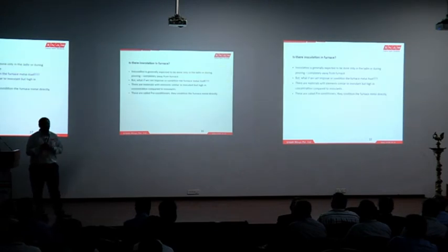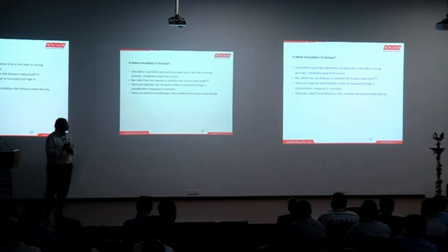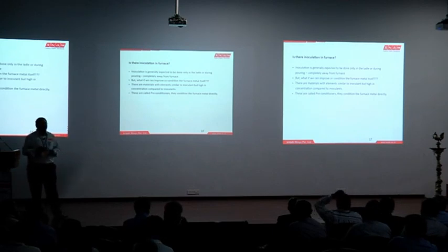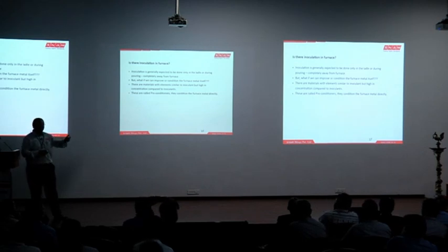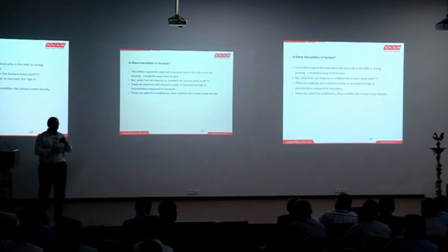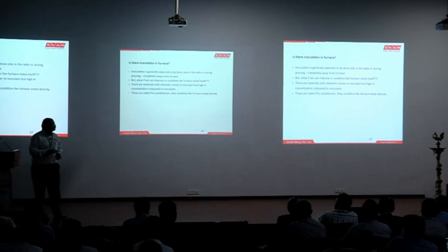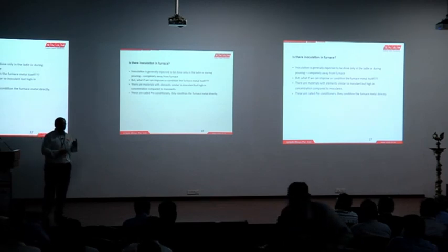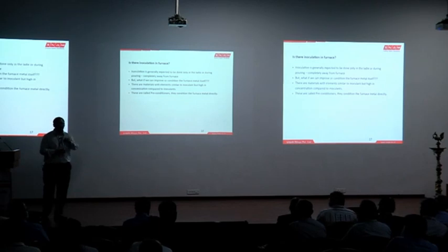Okay, we have been talking of inoculation in liquid metal after the furnace. Can we do inoculation at the furnace itself? Yes, it is possible. You can call it conditioning of the liquid metal. Whatever changes in demand of inoculation, or improved or varying levels of elements in the inoculation materials, have come up due to the varying potency of the raw material or the potency of the liquid metal itself. So if we can control the furnace metal directly, then you can work on the optimization of inoculation levels and the elements you want in your inoculant.